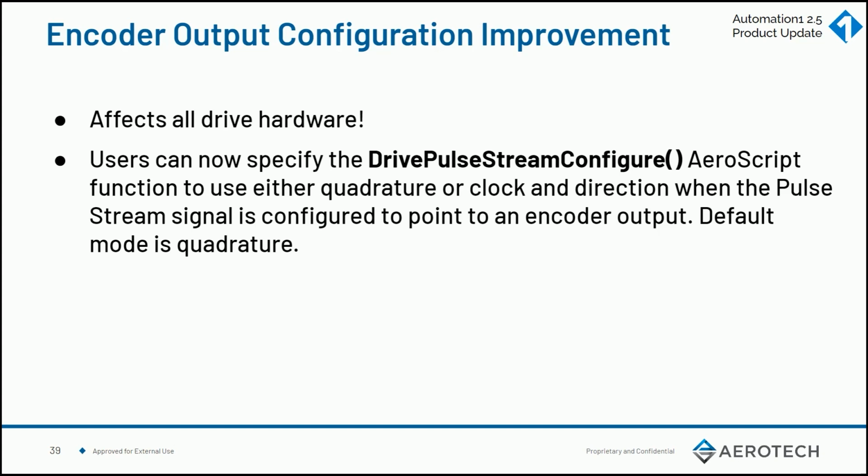They basically emulate an axis of motion, and we are sending these pulses to have an emulated axis of motion sent to the drive. You can send that emulated axis of motion as a clock and direction output to an encoder on a drive, and you can use that for anything your creative controls mind can tell you to do.